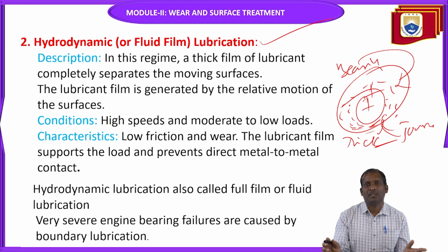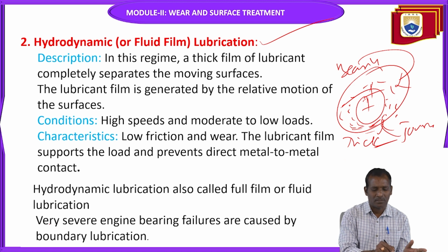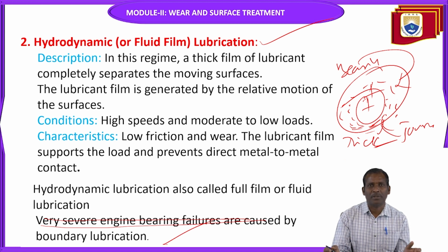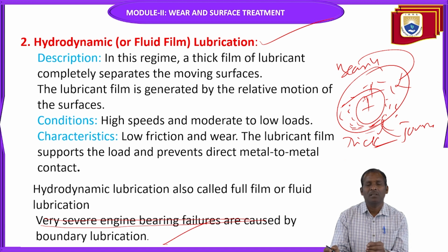Very severe engine failures do not happen here. In the case of boundary lubrication, some failure is possible, but in hydrodynamic lubrication there are no severe failures. Why? Because proper lubrication is possible in hydrodynamic lubrication. That's why this is called fluid film lubrication.